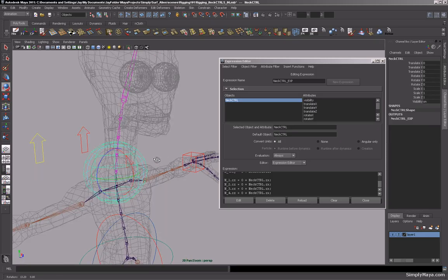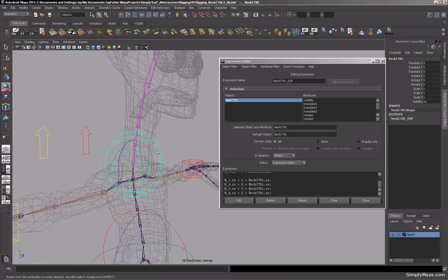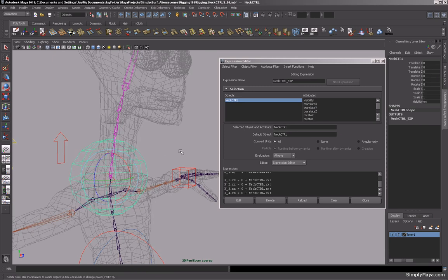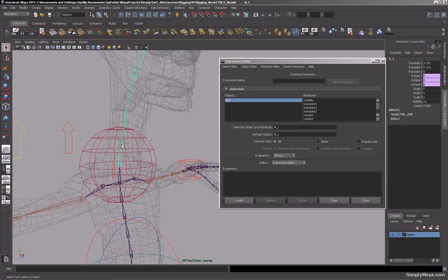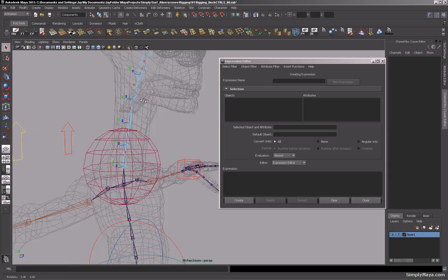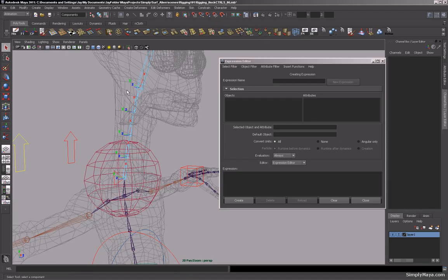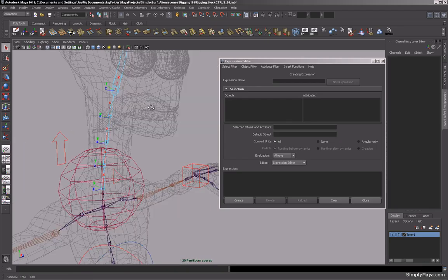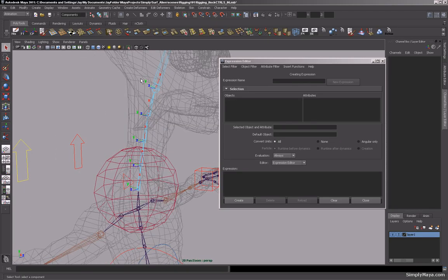But what we'll need to do is correct the joint rotation. Okay, so what we need to do for that is, if we go back and select our joints up to here, and then if you just hit F9, make sure your question mark for your miscellaneous components is selected as well, and you should get your local rotational axis icons appear.